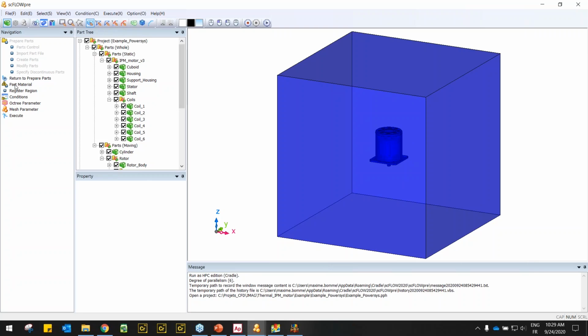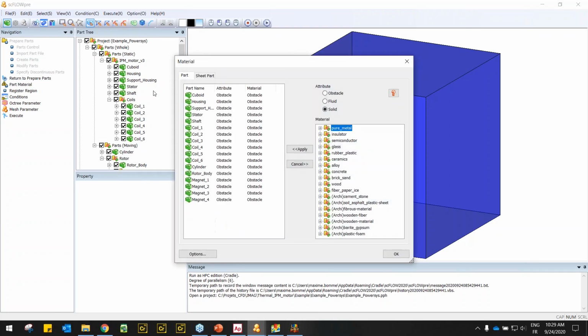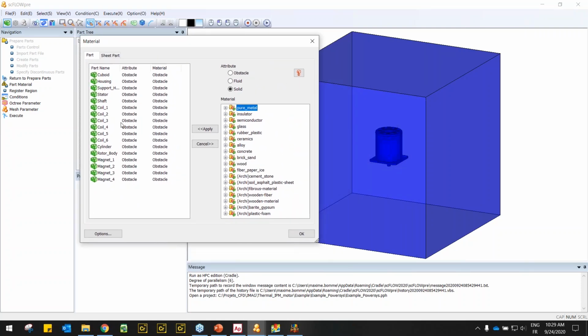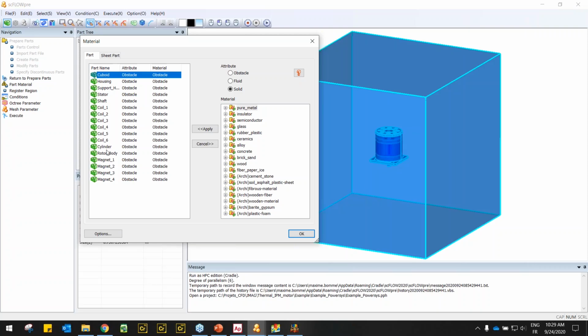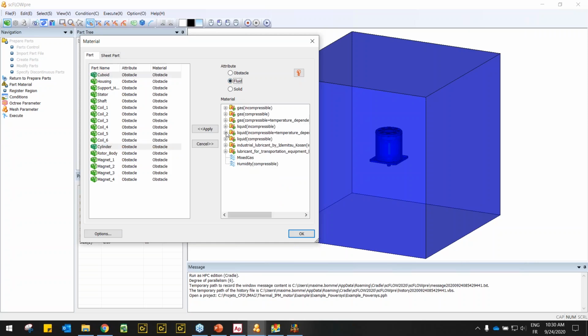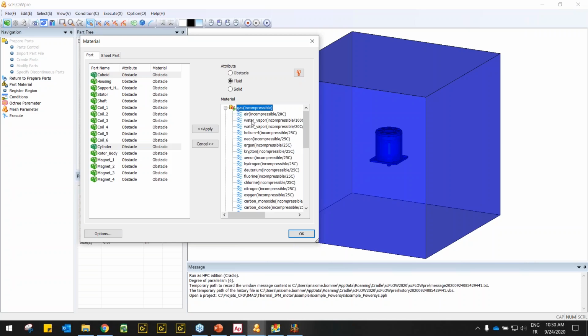Based on that, the interface is very easy. You go from the top to the bottom to the resolution of the simulation. Here, we will set up the material properties of each solid. For this volume that I created, and another one here for the moving area, I will just pick them and tell the software that it's fluid. What kind of fluid? Is it a gas? Is it a liquid? Is it compressible, incompressible? We have existing libraries with fluids and so on. Of course, you can create your own if not fulfilled enough here.